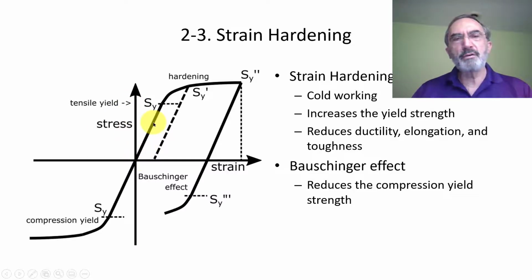So strain hardening means that, by now you know, if I put stress and I go up on this line, which has a slope E, modulus of elasticity E, eventually I'm going to get to this S sub y. And we know that if we exceed S sub y, we can keep on going, and I have to put more stress, but the modulus goes down, the slope goes down, no big deal. And we know that if we get to some point and then decide to unload, we're going to unload on a line that is parallel to the original. So the modulus of elasticity doesn't change because of plasticity. We go down, and when we get to this point, stop there, and now this is the permanent strain.